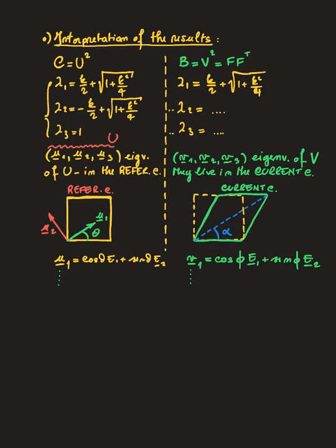In other words, this phi is not equal to alpha. This means that the mostly stretched fiber is at this angle phi here, and this would be the eigenvector v1, and its perpendicular would clearly be oriented in this way. Well, you would find that phi is not equal to alpha.